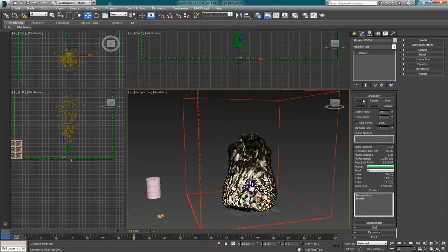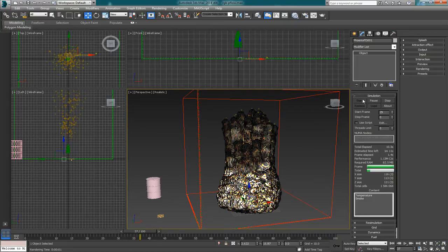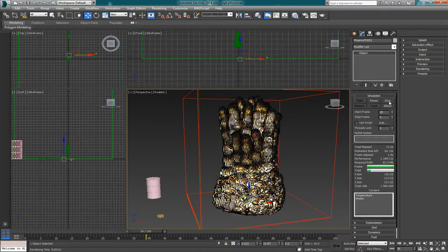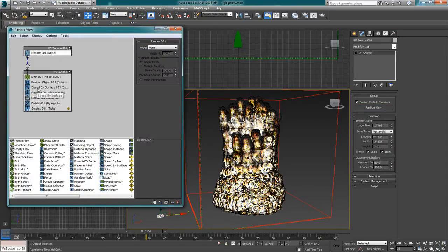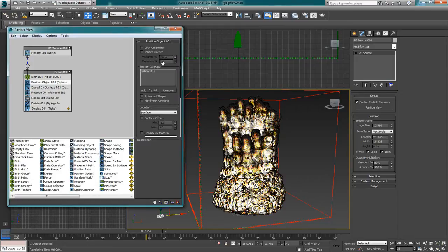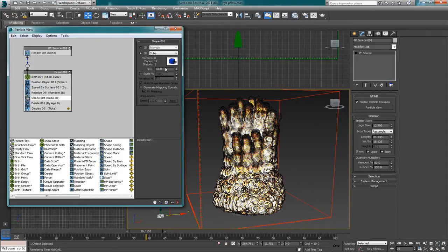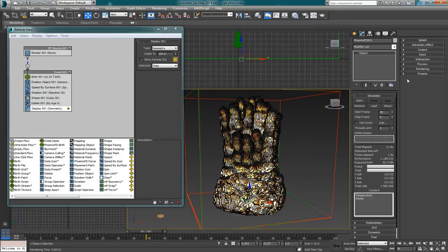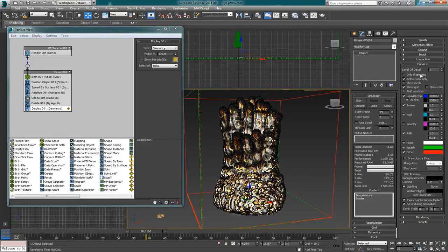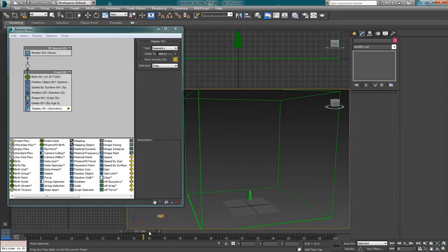Okay, so right now we have overdone it, and we need to decrease the size of the particles right here. So I will decrease it to 4, and I would also like to be able to see the actual particle geometry. Here from the preview options of Phoenix, I will check to preview only if selected, so when I deselect it I will be able to see the particles.